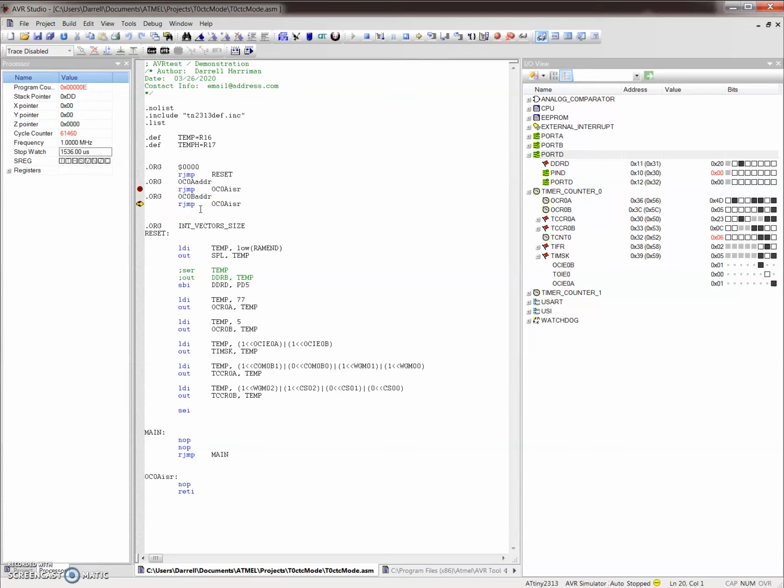So our servo position will be close to centered, and our servo frequency is going to be close to 50 cycles per second. And again, we have quite a bit of tolerance. It doesn't have to be exactly 50 hertz. We can do 48, we can do 55 probably, and be okay. So our timers are pretty good.